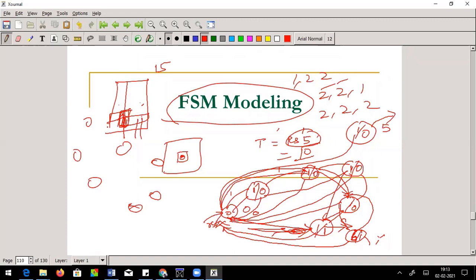As far as coding is concerned, the coding is a standard template, but arriving at a finite state machine, that too an effective one with the minimum number of states, is the real challenge. Why do I say minimum? The more states you put in, the more flip-flops you are going to have, and the more power consumption as well as resources required.